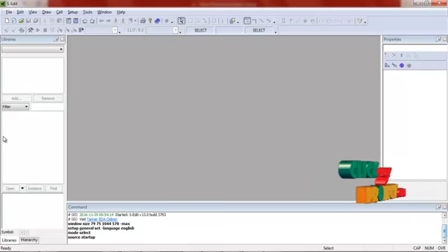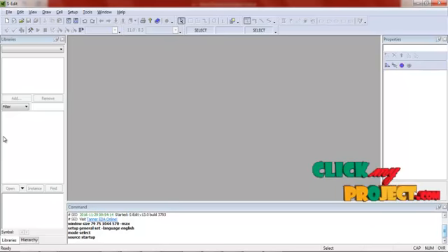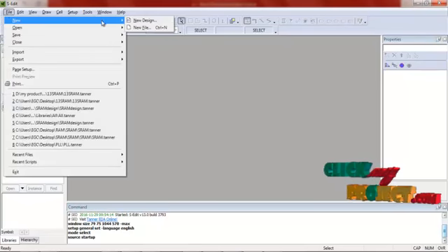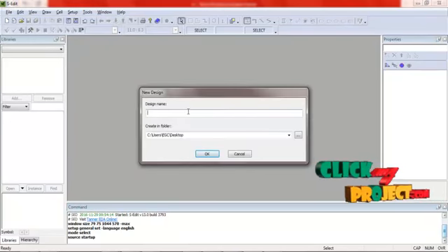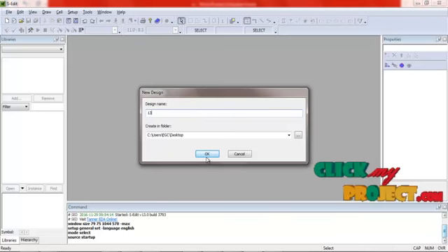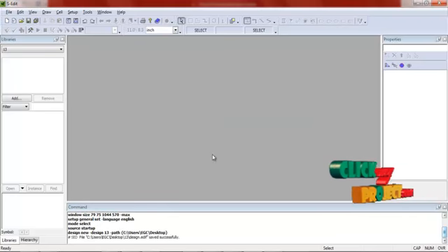Now we are going to discuss the running procedure of our product. In our product we are using the Tanner EDA 13.0 version tool. Now open the tool window and create a new schematic, using the file menu to create a new design. Assign the design name and the desired path. Assign the design name 13T SRAM, and after assigning the design name, click OK to continue.